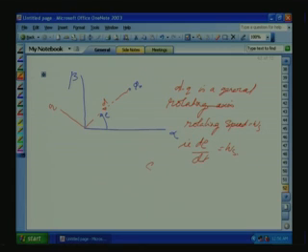Then the dynamic equations, if you are generating them based on this dq, are called the synchronous frame reference. If this dq is placed along the rotor axis, that means as the rotor varies, this d is also placed along the rotor axis, then we can say the dynamic equations developed on this dq are defined with respect to the rotor reference axis.